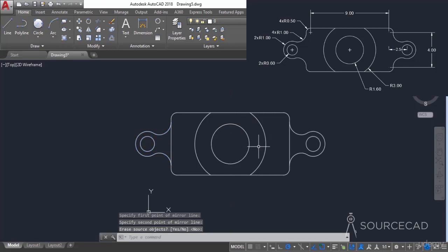Now we need to add a final detail and we can add it by removing these two parts. So I'll go to trim, press enter, remove this portion and remove this portion and press enter. So that's the final drawing which we were required to make.